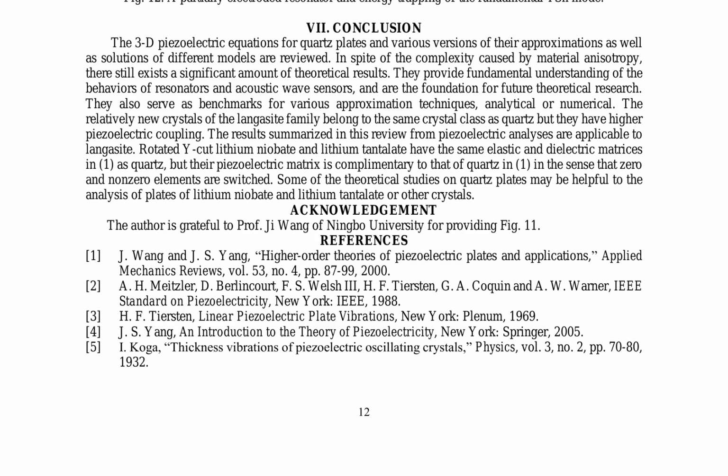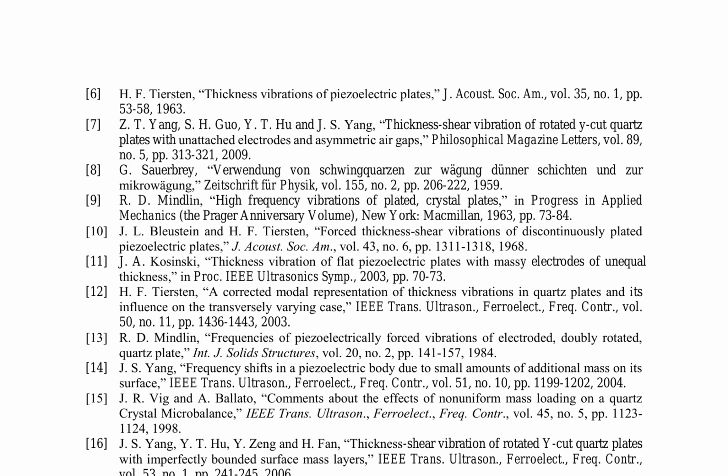The applicability of these results to other crystals, such as langasite, lithium niobate, and lithium tantalate, emphasizes the versatility of the presented approach. The paper's conclusions underscore the need for continued research into the complexities of piezoelectric behavior and its applications in sensor technology. Thickness shear vibration of piezoelectric plates, particularly rotated Y-cut quartz plates with electrodes of unequal thickness, is a crucial area of research. Previous studies on piezoelectrically forced vibrations, such as those by Tiersten, Yang et al., and Wang et al., have laid the foundation for this investigation.